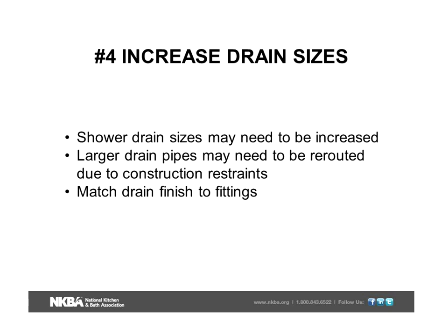Number 4, this has to do with shower drains primarily, but increasing drain sizes. And the points we're going to cover are shower drain sizes may need to be increased. Now, once we increase the shower drain size, then we may get into a problem where we have to reroute the pipe because now the pipe is too big for the construction restraints that are within the home. And finally, you want to be sure that you match the drain finish to the fittings.